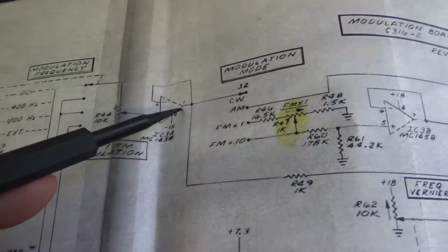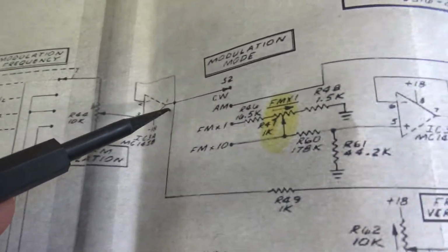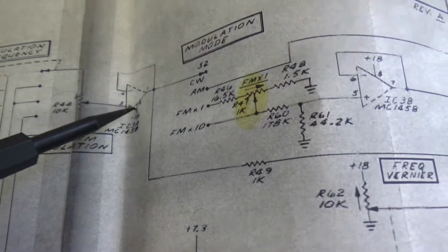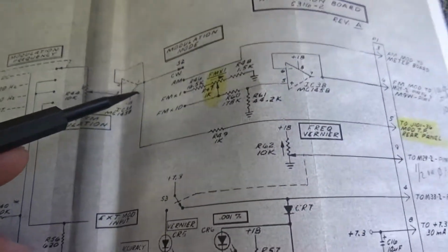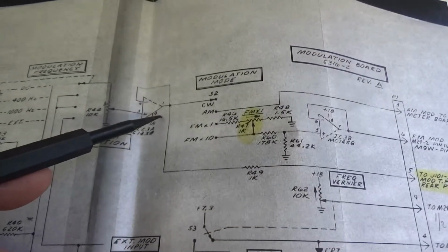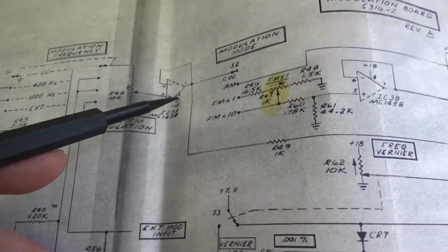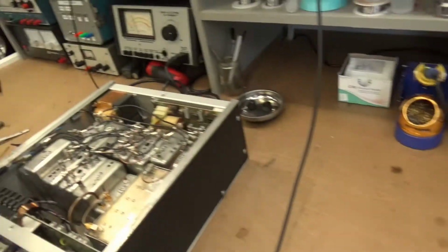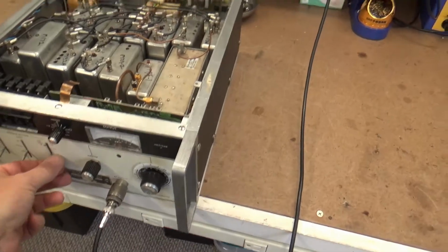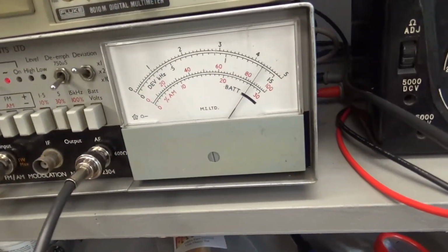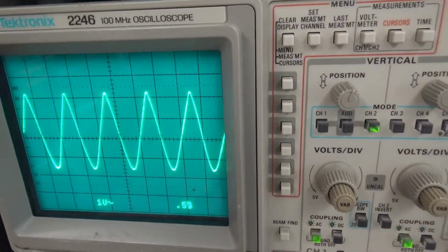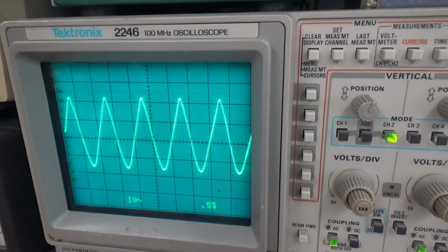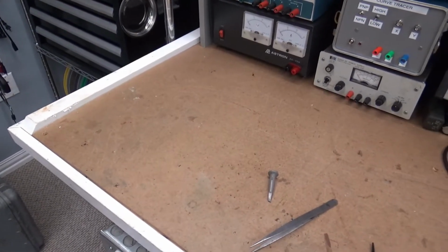So it's distorted. It's clean coming in right here, but it's distorted coming out, which means it looks like I'm overdriving this, and I'm not 100% sure that I actually have a problem. But I didn't have the op amp, so I ordered one from Mouser. So I'm going to turn this back up to 5 kilohertz deviation. I don't think this is going to be the fix, but I'm going to pause for a minute, and we'll change that IC, and we'll go from there, see what happens.